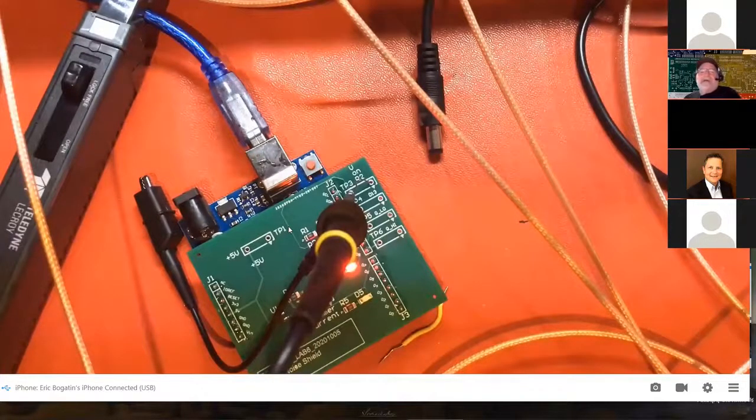So once you establish that maximum current, maximum voltage you can tolerate, that defines the resistance, you're going to be measuring voltages on the order of tens of millivolts in some cases. And that means you want a sensitivity in the millivolt range. That's the first condition for the differential probe. You want a noise level that is low enough to not influence the kind of measurement you want to see.